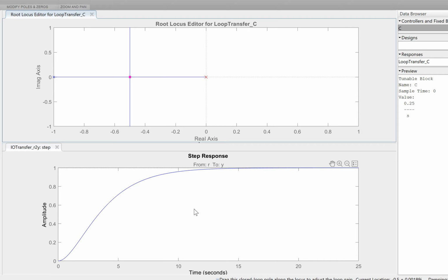Now, it comes at a price. Everything comes at a price in controls. It comes at a price, and it slows the system down. Okay, so if you're interested in speeding the system up, we're going to have to do something different. But if you are looking at reducing the steady state error, you should be thinking about adding an integral term to your controller. Okay, so we'll get into this a little bit more and do some calculations and get some details on this.